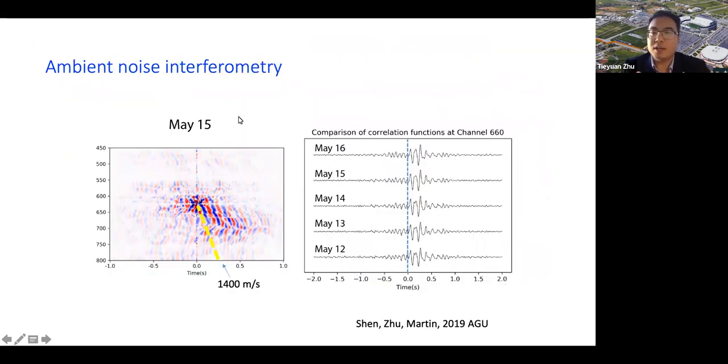And we can also use the ambient noise for subsurface imaging. As you can see, after we do all this noise cross correlation, we end up with a Green's function for each day. For example, for this particular week, there are not many near-surface variations, so you see the Green's function is quite stable. We would expect that if there are lots of rainy days or groundwater variations or some other variation in the near surface, this Green's function would show an indication.